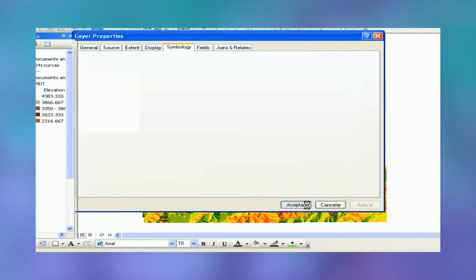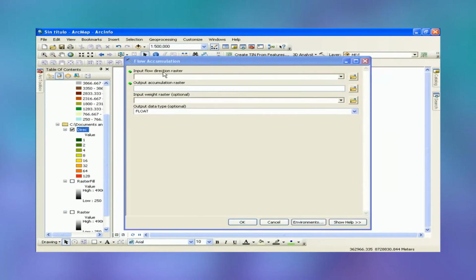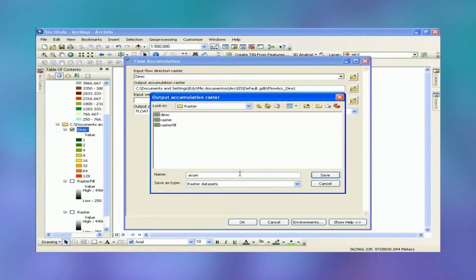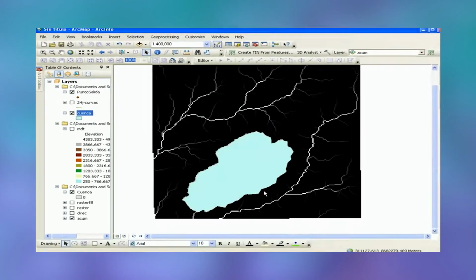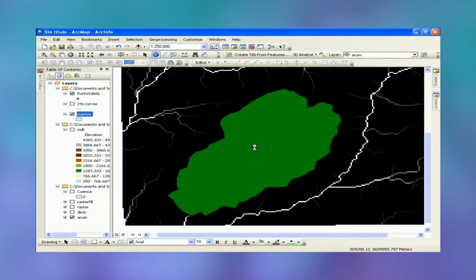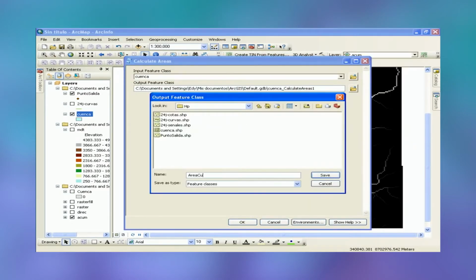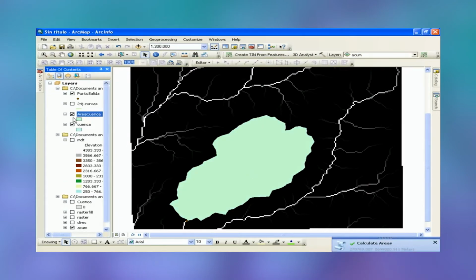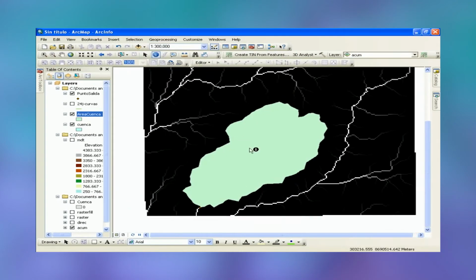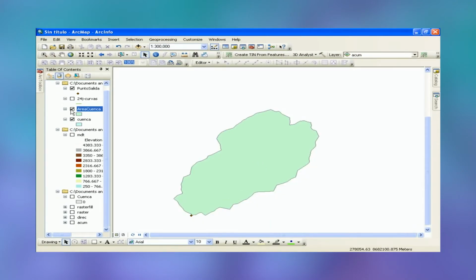Creation of slope maps. Slope is the main factor that determines and differentiates the shapes of the landforms. Thus, the slope of the terrain is in terms of mathematical ratio determined by the proportional relationship between the difference in altitudes and the horizontal distance between 2 points. The slope can be expressed in percent or sexagesimal degrees.